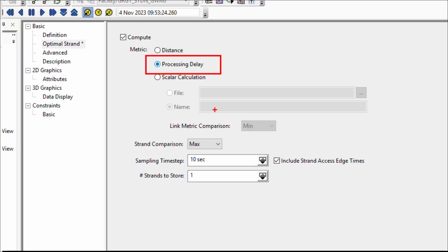Processing delay is an important metric to be taken into account. It is a noticeable latency due to the speed of light when sending data to and from satellites and the distance between the satellites. Speed of light is constant, but other delays could be caused by hardware and software and every device that the signal must pass through. The default processing delay for your objects in this particular scenario is 0 seconds. We can change the processing delay for one of our objects to see how this works in STK 12.8.